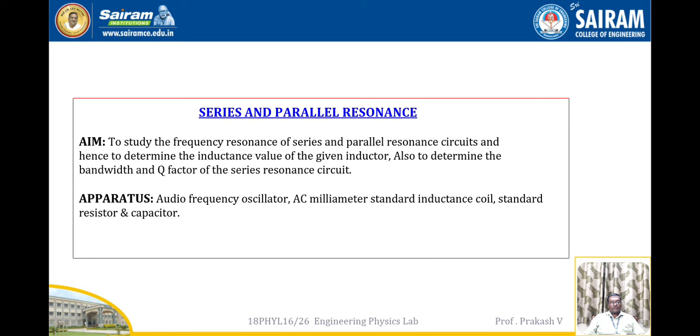The aim is to study the frequency response of series and parallel resonance circuits and hence to determine the inductance value of the given inductor, and also to determine the bandwidth and Q factor of the series resonance circuit. Apparatus: audio frequency oscillator, AC millivoltmeter, standard inductance coil, standard resistor and capacitors.